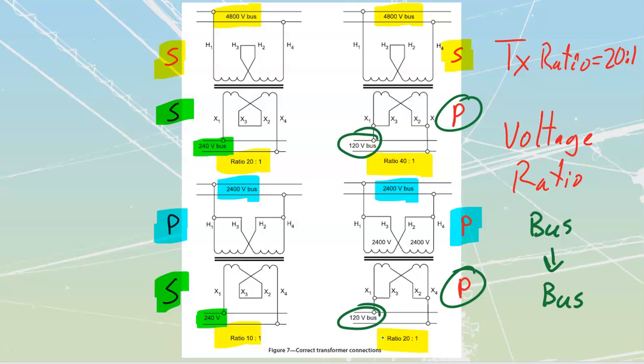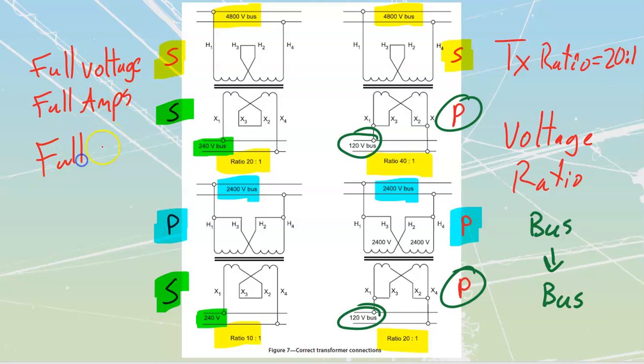Any one of these transformers is going to have proper connection of each coil. I don't care which one you would pick or which coil you'd want to take a look at. You'd see that each coil has got proper full voltage. And because each coil has got the proper full voltage, it's going to have the proper full current, which means that if it's got the full voltage and the full current, it's going to have the full VA. All of these individual transformers here dump out 100 kVA onto this low voltage bus. It doesn't matter how that connection is made, but we're getting full flux on the primary, therefore we're getting full generation on the secondary, full amount of current that we have capable of coming out of it.